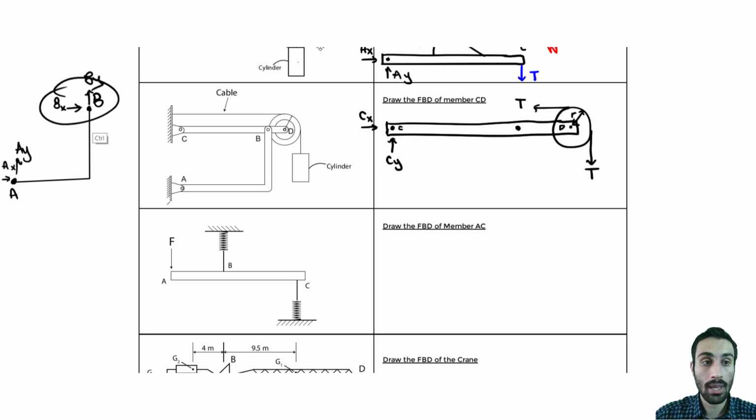And we know here when you have an X component, Y component, you have a magnitude. And when you have an AY, AX, you have a magnitude force, right? And that magnitude force is actually the same. For a two-force member that is only loaded at the ends, the magnitude force is the same. So we will approximate and say, okay, that magnitude force would probably look like this, and it's going to have the same line of action, right? It will always have that same line of action, and it's a force, and that force here, note, is the same as the force here at A. So that's why we call it a two-force member.